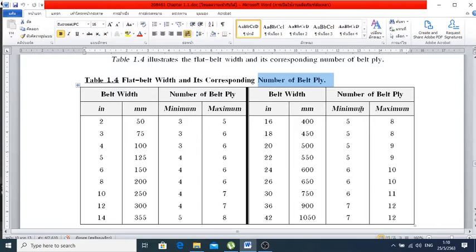And then if we apply more plies, we do the same manner to put everything down. The more plies, the more money you're going to pay to apply them, and of course, if you have more plies, it means you have more strength, more power to be generated, things like that. So this is the thing that we're going to consider. We're going to do the optimum design with the number of plies.